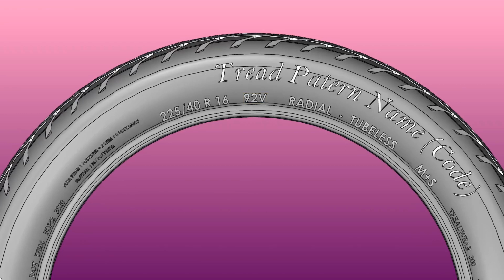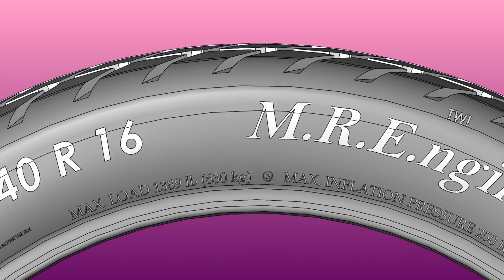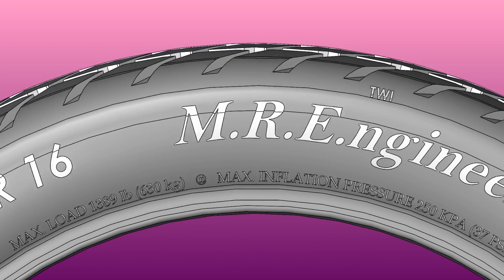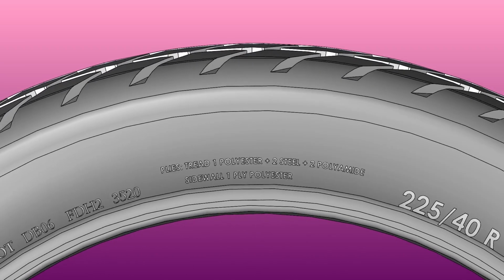According to the European standards, the 2 or 3 digits show the load index and the letter is known as the speed symbol. About this service description, I will explain in the following. But according to American standards, the load capacity of the tire is indicated by maximum load, and the tire also has to be marked with the maximum pressure that the tire needs to be inflated to bear this maximum load. Tire ply composition is another piece of data that is mandated by Americans to be marked on the tires.